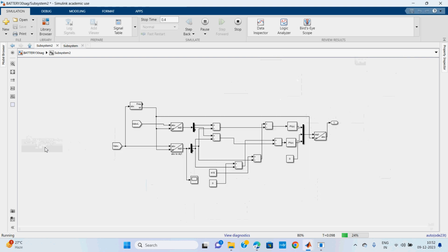And this is the control strategy. This control strategy is named synchronous reference frame theory. Here, we compare two voltage parameters to get the error: one is VL minus VABC. I took these two parameters because first of all, I want to know how much compensating voltage we need to inject from the DVR, right? For that reason, we select these two terminals: load voltage minus sending end voltage.